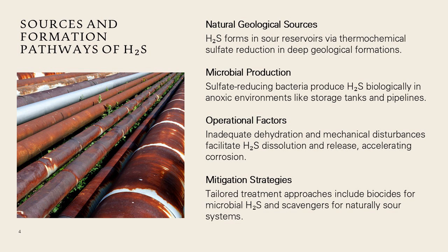Other contributing factors include inadequate dehydration processes, which allow water to accumulate, facilitating dissolution of H₂S and accelerating corrosive reactions. Mechanical disturbances, flow regime changes, or the introduction of incompatible chemicals may also liberate trapped H₂S from sediments or emulsions. Understanding these pathways is crucial because each formation mechanism may demand a different mitigation approach.